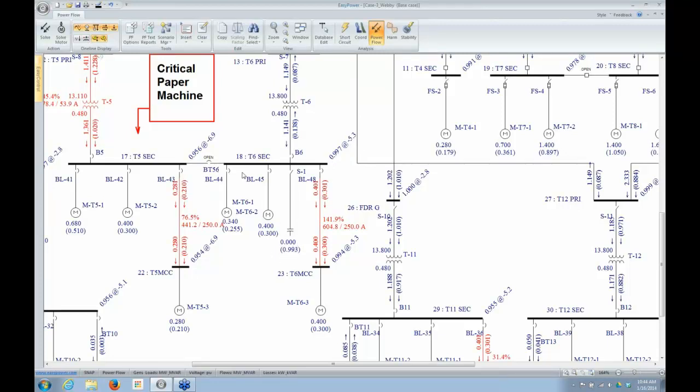So when I add caps, one of the issues is that they're always there unless I switch them. So I have to be a little bit concerned. In this case, if I have a fixed bank of capacitors that's always on, what's going to happen when I have no load? I could just basically double click on each one of these breakers to open them up, and I can watch my voltage increase. This is a little high, but it's still within my 0.105 range that I allotted for. So this is just a good way to check your system voltage when you have no load. Make sure you're not going too high.